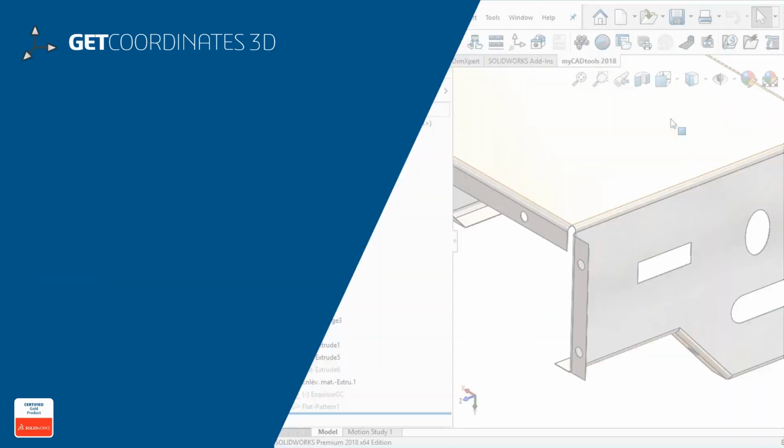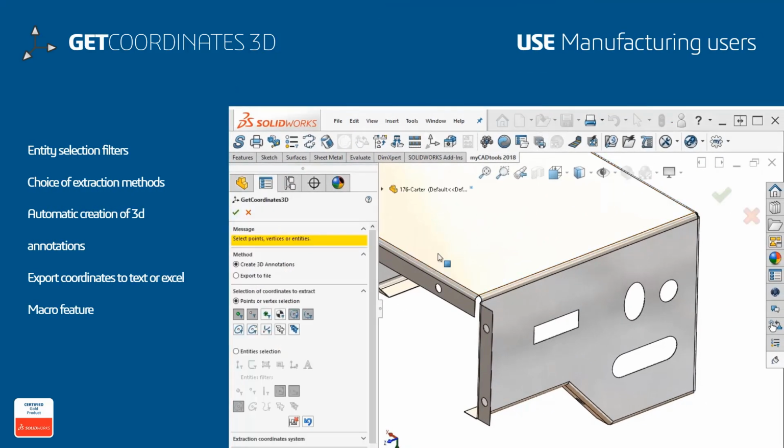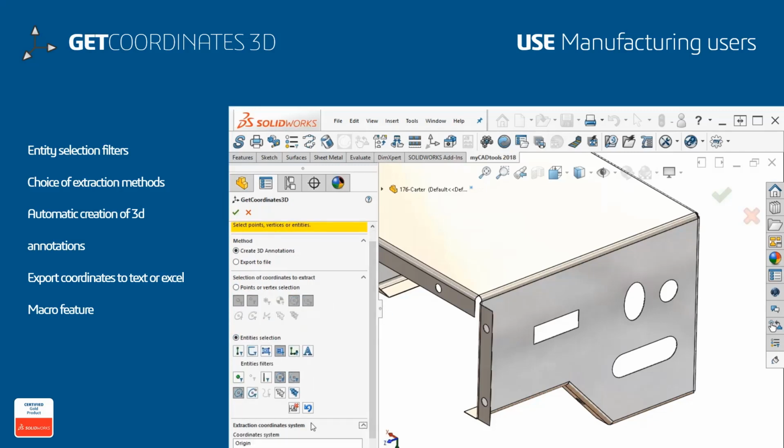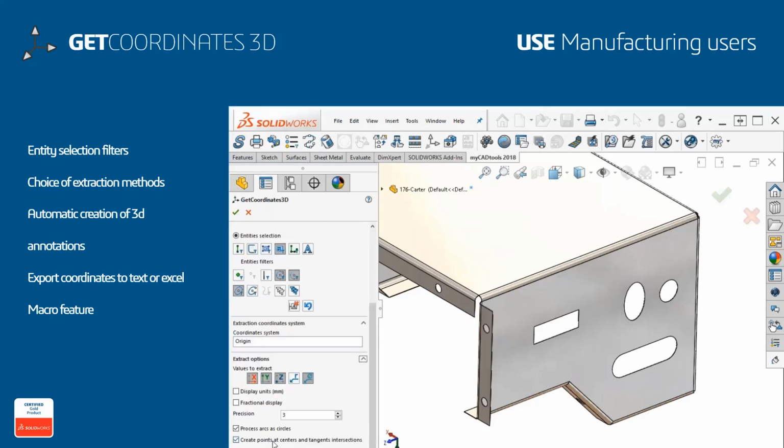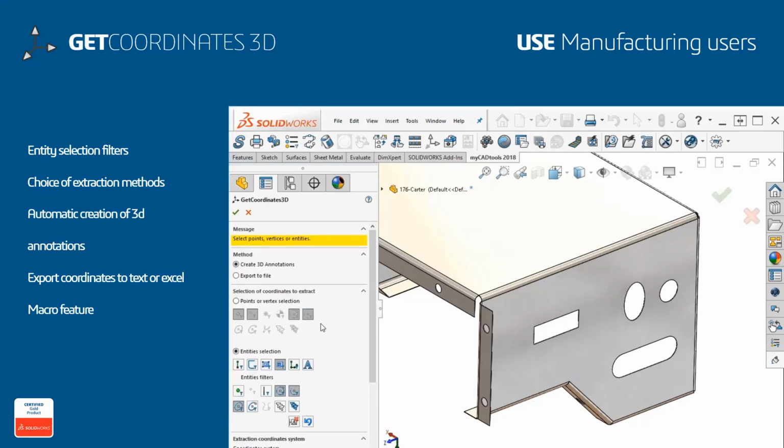Get Coordinates 3D. Get Coordinates 3D enables you to create labels automatically for a part or assembly to display coordinates of vertices or entities. You have a choice to create 3D annotations or export the coordinates to a text file. You can select points or vertices with filters available to help. Then choose your extraction reference. You can then choose which values are extracted and their format, useful for adding specific annotations to your 3D models.